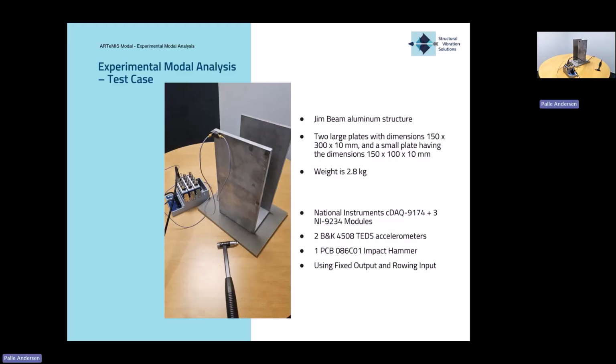And you can see again the same that we have our 2 accelerometers here that are sitting here. We have our data acquisition system here. We have channel number 1. This is our impact hammer here that is connected to that one. Channel number 2, that's the accelerometer we have here that is going this direction here of when it measures. And then channel number 3 is the one that is going in this other direction here. So there are these 3 channels in use of this data acquisition system here. Let's try and start the software up and then see what we can get.